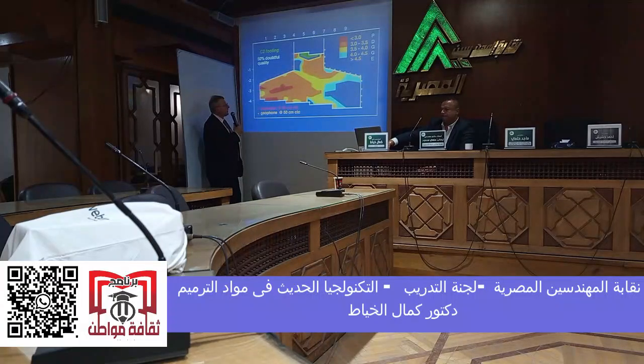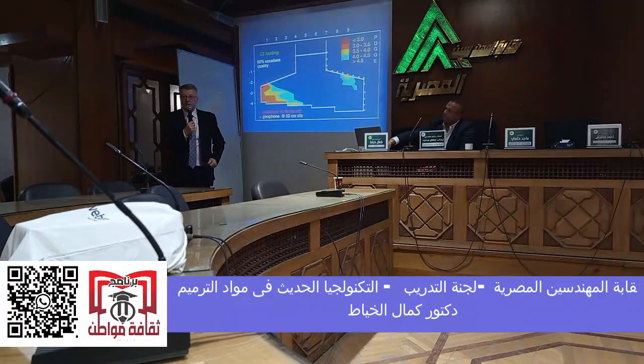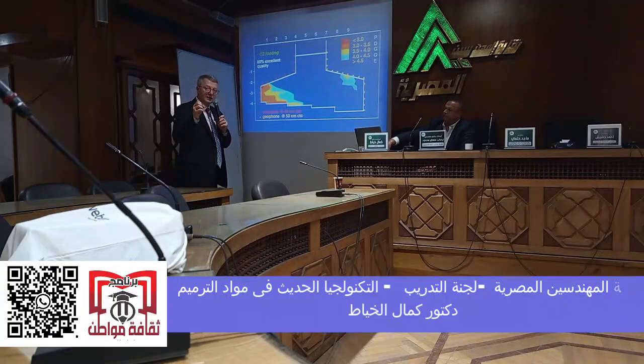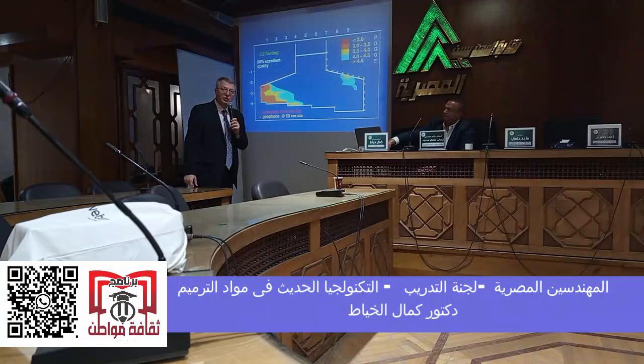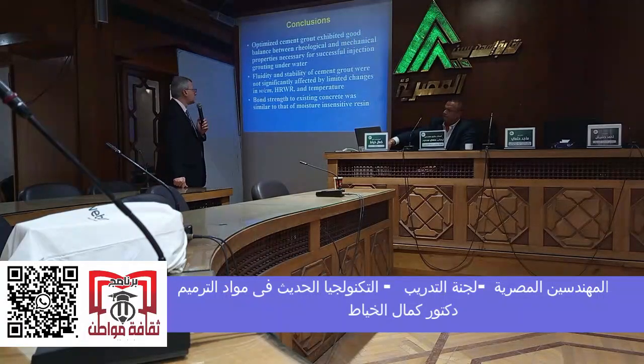Next. This was before the repair, and look at the color now, it's going to be mostly blue. Next. This is after the repair. After the repair, most of the concrete is now dark blue, which is 4.5 kilometers per second. Again, it reflects the elastic modulus. It reflects that you have done a good job on the repair. Next. It's a perfect repair. MashaAllah.